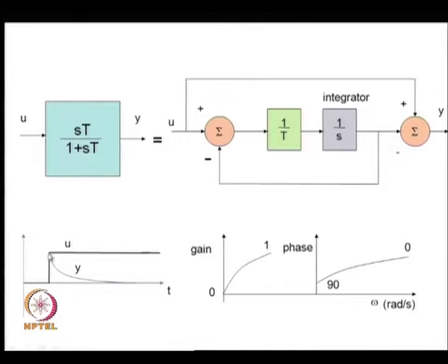It has some response initially, a gain of 1 during transients, but it eventually kills out the response in steady state. So, remember that in any stabilizer you will find that there is a washout block of this kind to remove any offsets in the signal U, so that a stabilizer does not actuate the controllable element under steady state conditions at all.